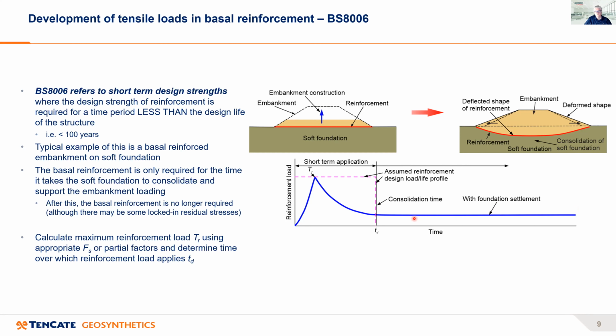Now, from a design point of view, we're interested to find out the maximum load in the reinforcement. We're also interested to know how long it takes for the soft foundation soil to consolidate and support the full load of the embankment. So we're interested in this level, TR, and the consolidation time.